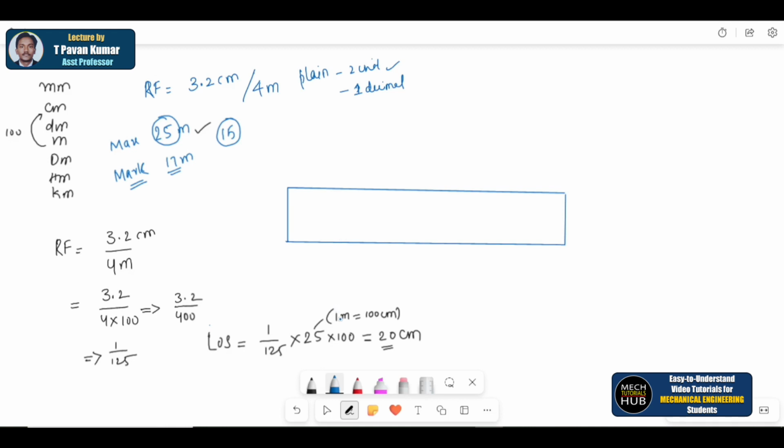Okay, so the length of the line that is drawn on the sheet is 20 centimeters, which is calculated from the length of the scale. That is fine. This scale is to be divided into 5 parts. I'll try to divide this complete length of 20 into 5 parts, 5 divisions. Why 5 parts? Each part will measure 5 meters. Okay. So here, this is first part, second part, third, 4 and 5.